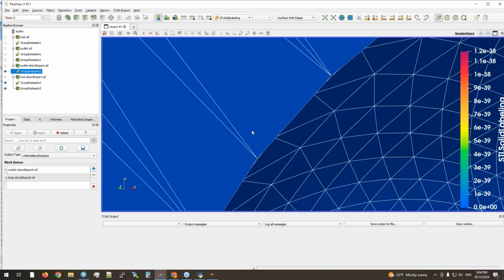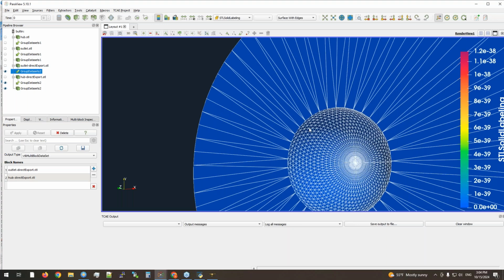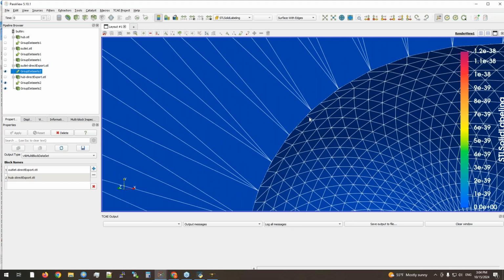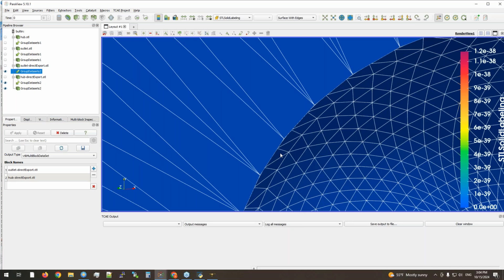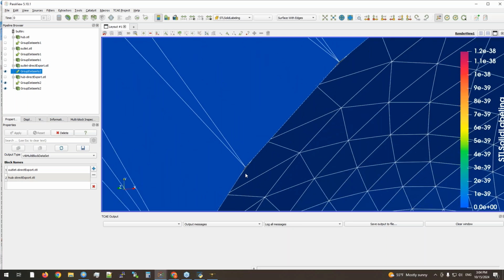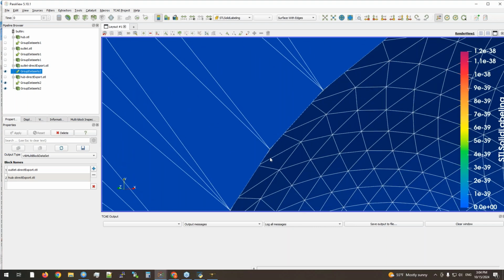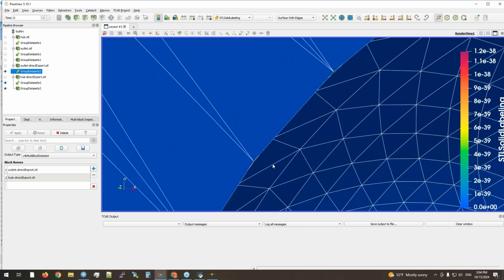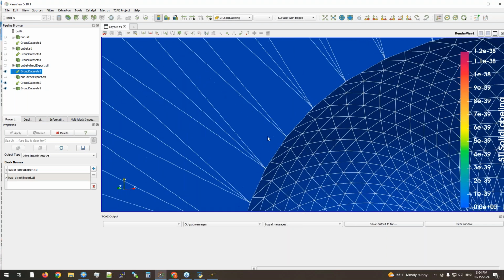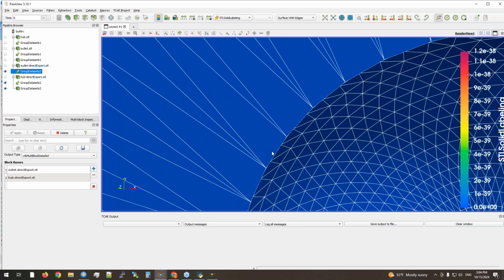Because each part was exported separately, there are some big triangles and smaller triangles, and they are not topologically the same, which creates such holes. This can bring problems to the meshing, because the input STLs are not perfect and it can cause some trouble in the meshing part. Therefore, I do the first triangulation numerically, and then export this triangulation as the STLs. This is the reason why I did it this way.